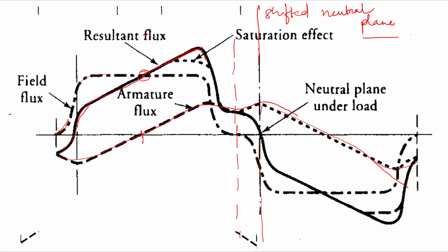The rotor is rotating. We should fix it in the stator. You are correct, but we have to fix it in the stator. So now the question is, where do we need to fix those poles or magnets in the stator? In the neutral plane itself. Okay. So those are known as the interpoles or compensating poles.